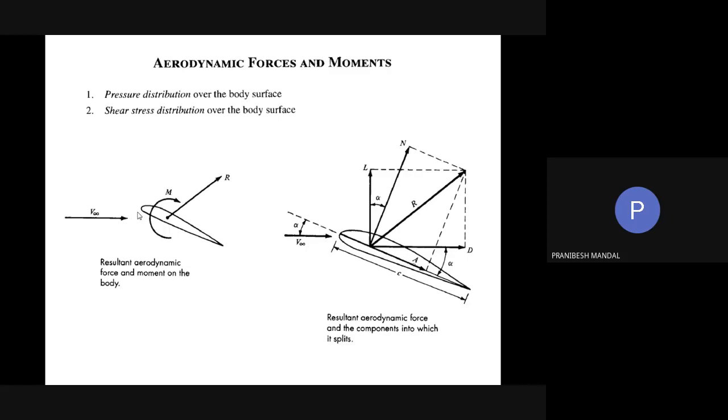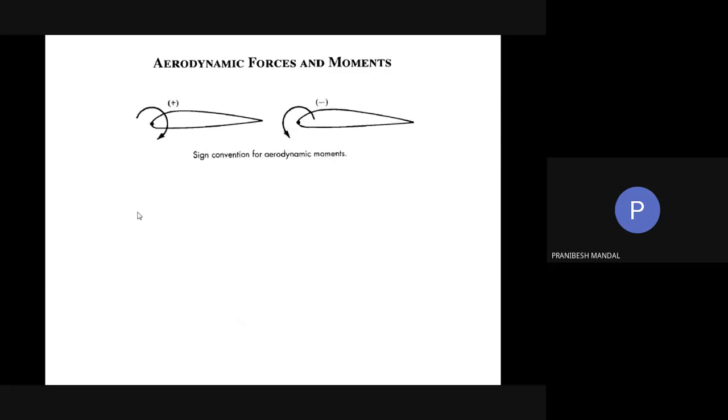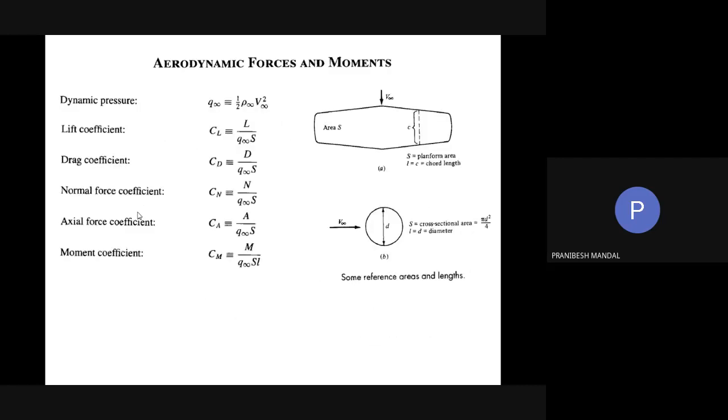And in the dynamic pressure, rho infinity also denotes that the density of air is taken a bit away, because at the nearest points to the object, the properties can change due to disturbances. So the free stream conditions are a bit away from the object.